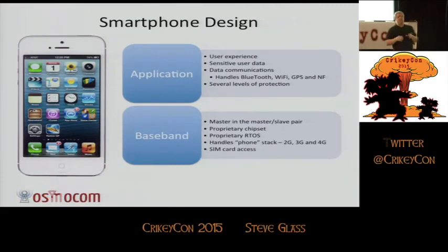It's actually only available from a small number of manufacturers. And those manufacturers are subject to very strict licensing conditions. In order to get their firmware validated, they submit the whole lot to the appropriate telco authority, and they get it assessed, and they say, yes, you've got a big stamp on it. But in order to be allowed to connect to the telco's infrastructure, they have to make sure there's a very narrow interface between the rest of the system and that processor. And the way it's done is typically that it becomes the master in a master-slave relationship.